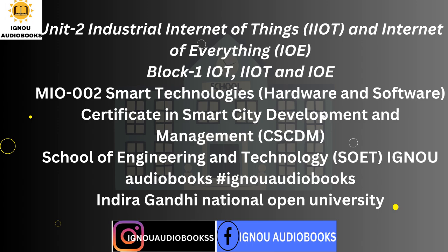Cybersecurity. Cybersecurity is a very important consideration. Multiple options exist to pass data into the cloud to enable enterprise-level or outsourced third-party connected services. The most suitable security solution can be selected depending on the connected service provided and the architecture of the plant automation system. Options include but are not limited to backhaul network, demilitarized zone (DMZ), data diode, physically private network (PPN),